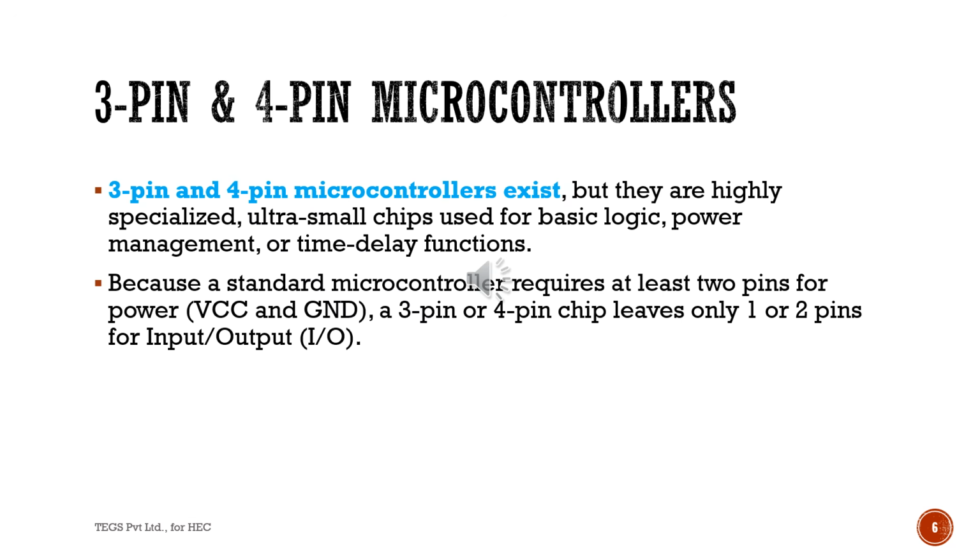3 and 4 pin microcontrollers. 3 and 4 pin microcontrollers exist, but they are highly specialized, ultra small chips used for basic logic, power management or time delay functions. Because a standard microcontroller requires at least 2 pins for power, a third pin or fourth pin leaves only 1 or 2 pins for input-output operation.